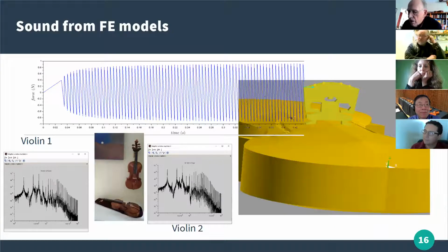The other thing is that, of course, the frequencies of those modes, and particularly the breathing mode, the B, which is involved in both the B1 minus and B1 plus modes, is very dependent on the interaction of the air inside the instrument as well. So that's another thing that makes the actual thickness of the plates less important than you might otherwise expect, thinking that it's just a simple thin shell type of model.